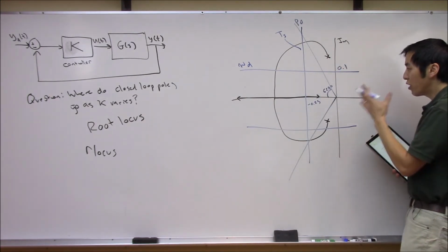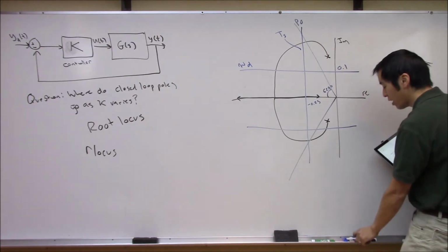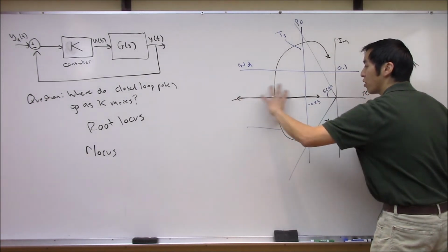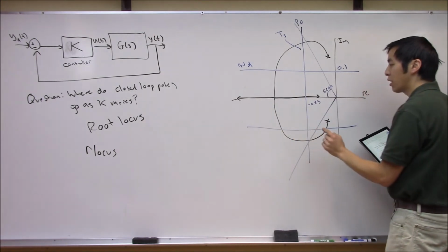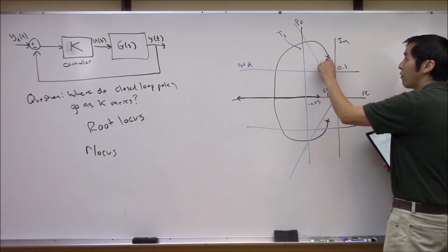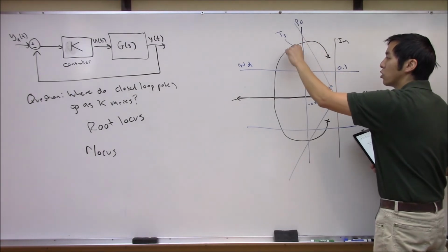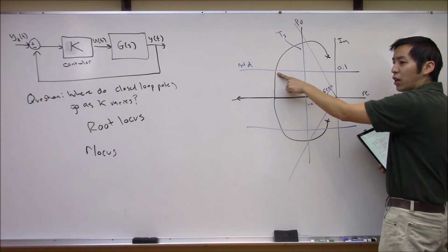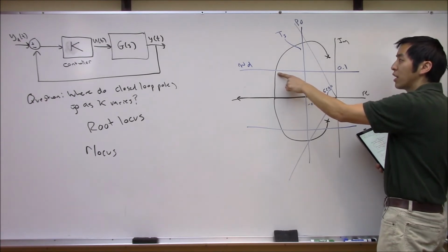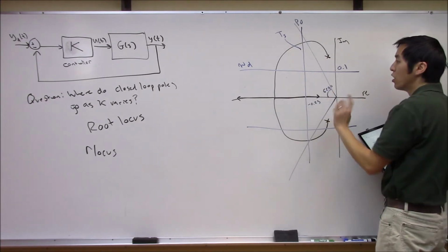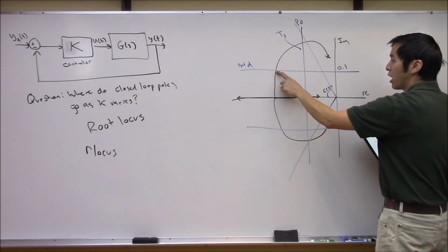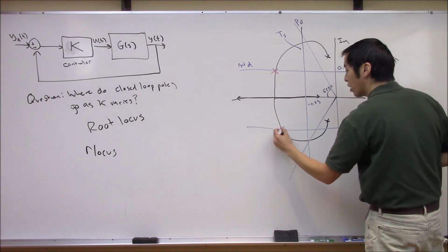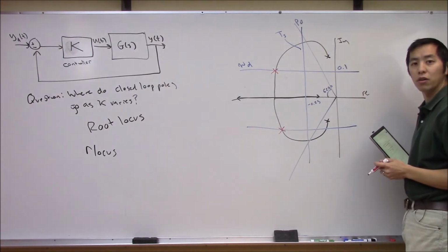Now, with this picture, doesn't this look really interesting? Because what you can see is that you have to end up in this region. This rectangular region is what we were talking about. So the game plan now is to find the value of K that pushes the root locus just far enough so that it enters a region of the complex plane which simultaneously satisfies all three of these requirements. We can see from this picture that it's probably going to be this location right here. Let me circle it in red. So we want to put the poles right there.